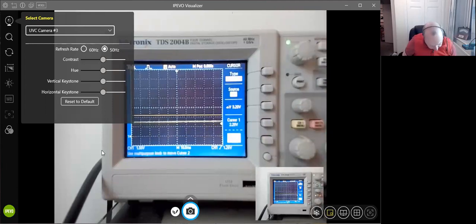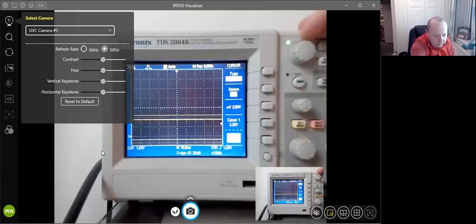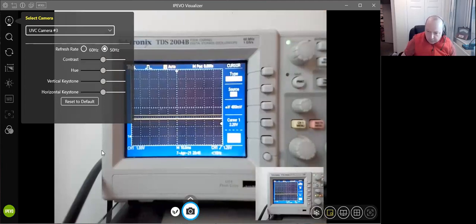Right, and the answer is to the same level. Guess what? It looks like it's slightly lower. So the moral of the story here is that when you've got your sensors, obviously you're going to have to calibrate for whatever the fluid is. Who would have thought there is a difference between distilled water and tap water? I can only guess. I'm sure somebody will know better than me that it's maybe the minerals within it.